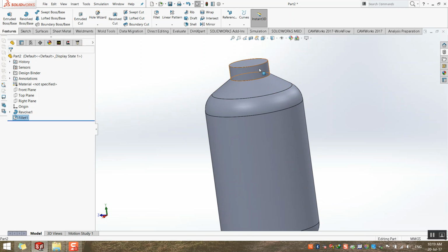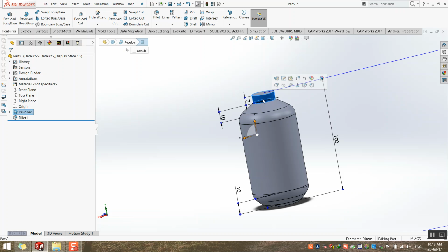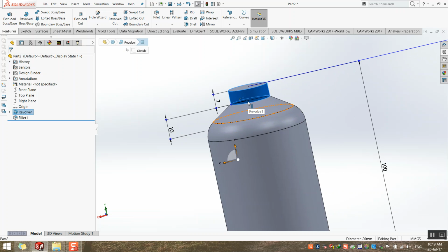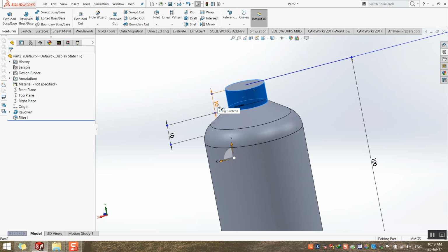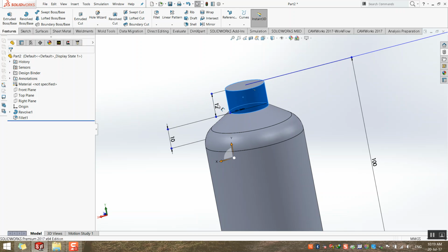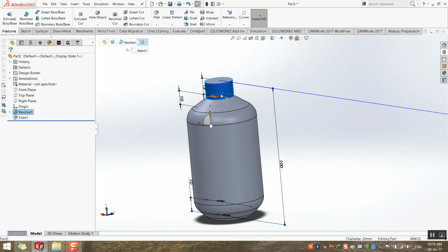Now I need to change the dimension of the neck. So automatically, as we said yesterday also, when you click on the model, it will automatically display the dimensions of the sketch and feature. These 7, click, one click on 7, 10, 12. Okay. Reduce from the total height.